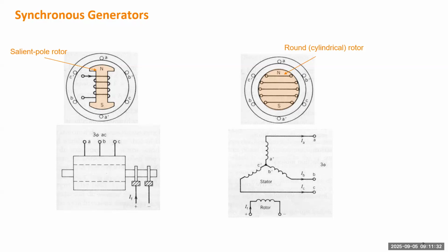So the rotor will have a single winding, which is called the field winding. It will carry a DC current. The current can be from another DC source or from an AC source through AC to DC conversion. This DC current will generate a magnetic field. Under static conditions, the magnetic field can be constant, but under some transient conditions, you can add some control to this field current to influence the magnetic field,